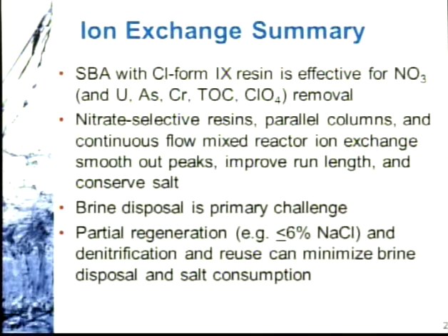And while current treatment costs for standard strong base anion exchange applications might be on par with some of the other technologies in some cases, whether it be reverse osmosis or biological denitrification, the opportunity to decrease the capital and O&M costs for strong base anion exchange is still tremendous.